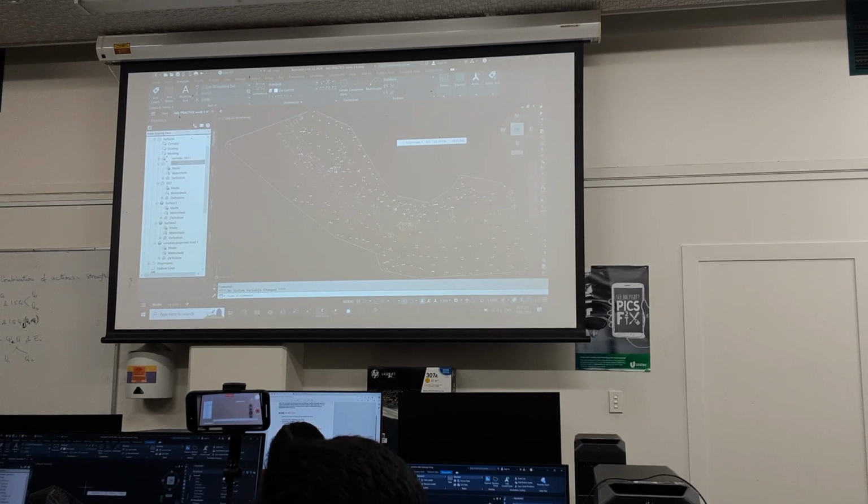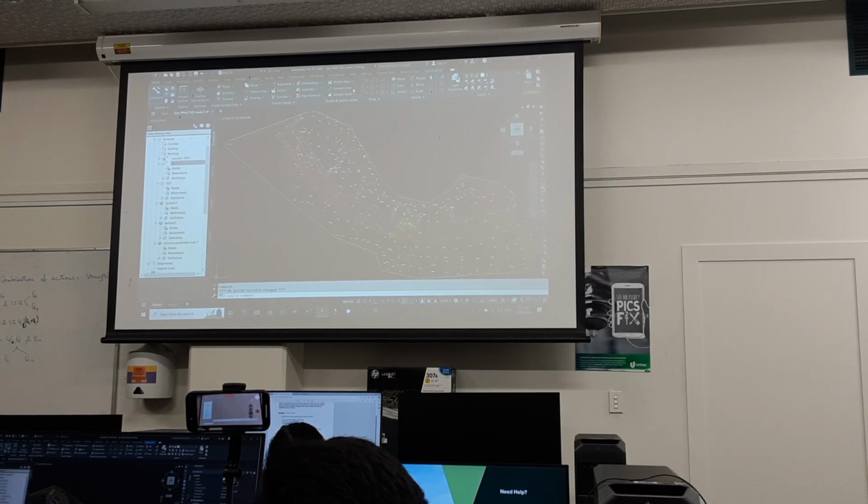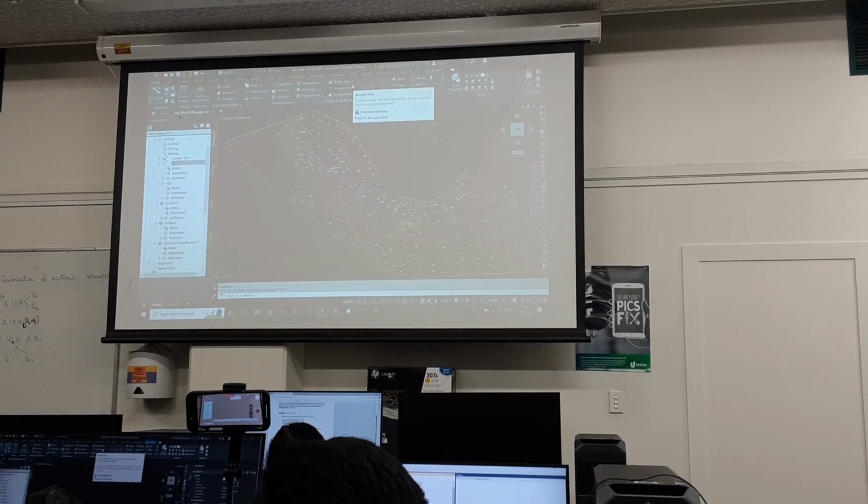Okay, so we're now at the stage of producing cross sections. The notes themselves say that the first thing we need to do is do the lines. So under the home button, up the left, back to where we normally are, you'll have a look and you'll see something called sample lines. You see that?